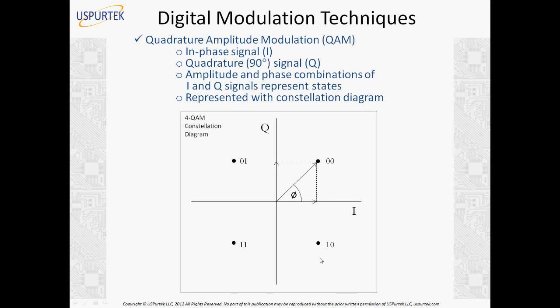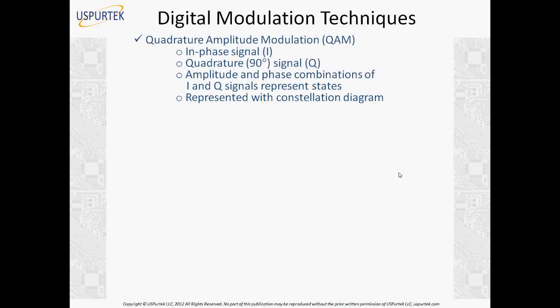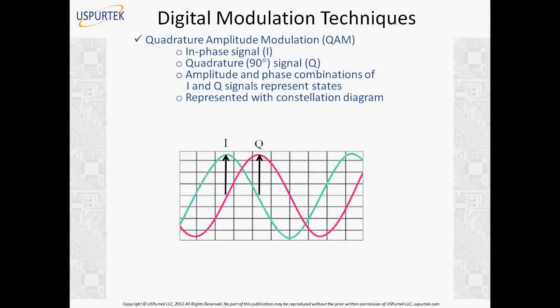Before we look at the next slide, this is a more physical representation of the signals. If you see the signals on the scope, you will see them like this: the I signal and Q signal, 2 sine waves. Actually, this one is called sine and this is called cosine, because it's at a phase difference of 90 degrees. The peak of this is at a phase difference of 90 degrees from the I signal. So this is how the signals will actually be physically transmitted.